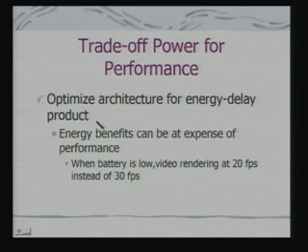The other thing is, we have already looked at voltage scaling. One point is for the purpose of meeting the deadline. The other thing is that you can also optimize the architecture for energy delay product. We have already seen that energy benefits can be at the expense of performance. Earlier, when we were talking about the OS, if you have a deadline, the OS would schedule voltages and frequencies such that you are meeting the deadlines. But many of the deadlines for many of these embedded systems are soft deadlines. Let us say a CD player or a DVD player, they are soft deadlines.